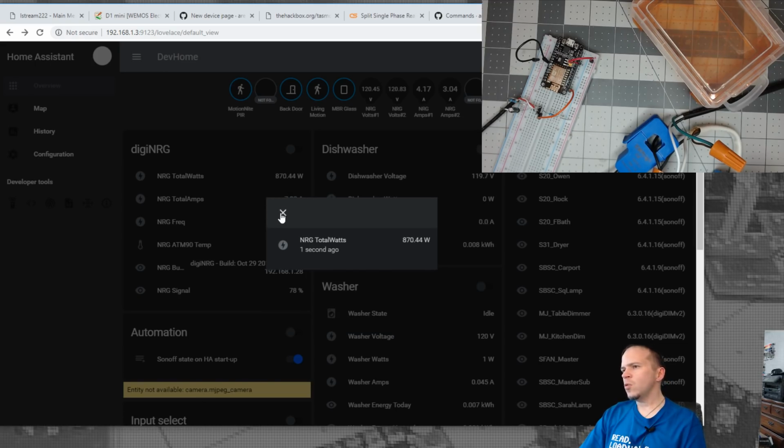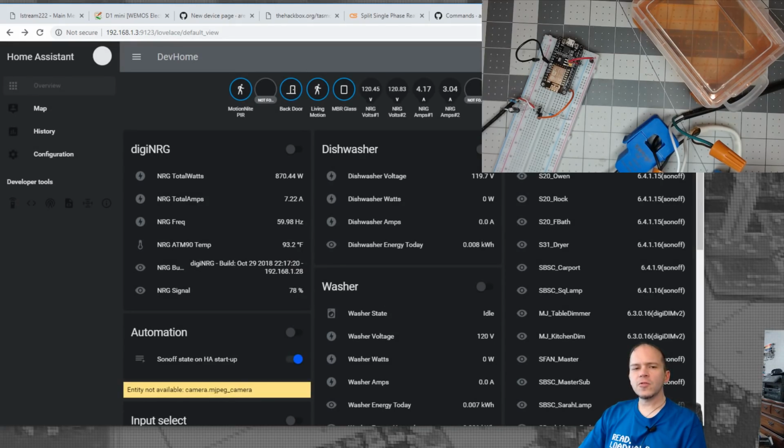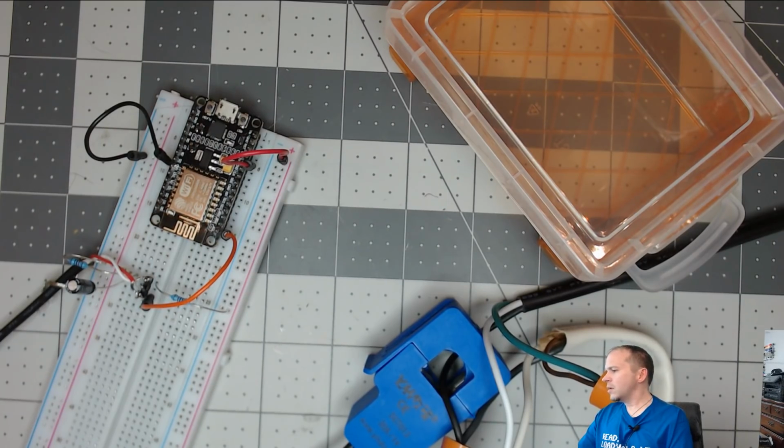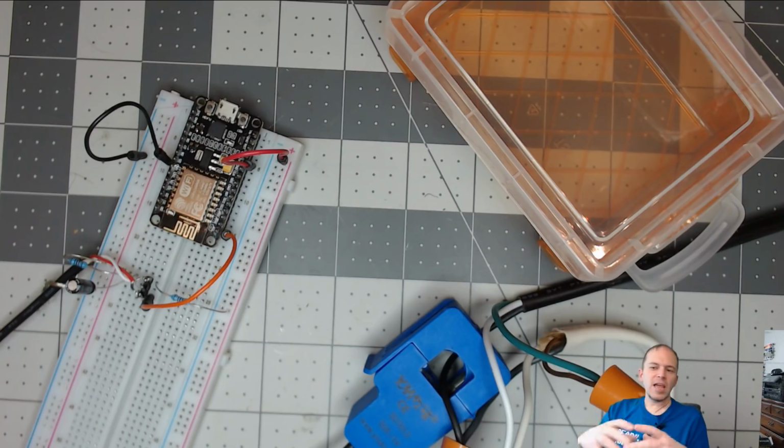But that's for a whole home. And if you add one in, you could do the option of putting it in the panel, if you don't want to put it on the actual dryer. The reason why I say I put it on the dryer itself is because it's much safer for people: you just unplug the dryer and then you can mess with it, put the clamp on it, etc., without having to worry of getting shocked.